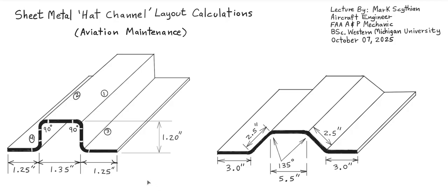So the actual working length is known as the mold length line. This includes the projection of the bend on both the horizontal and vertical axes, called the setback. So if we were to subtract the setback from the mold length line, we would then get the flat value.